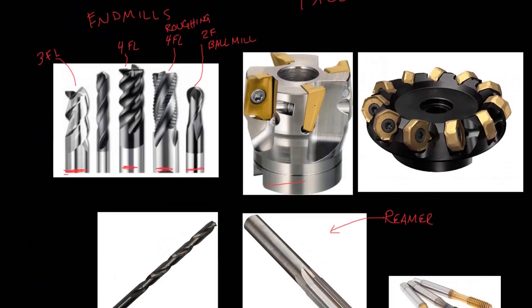You know, don't quite mill out the edge that you want on the pattern, but you could come in and go super fast like that, and then come back with a regular end mill, like this 4-fluted end mill, and then you could just profile out the nice edge of your pocket that you want, like that.